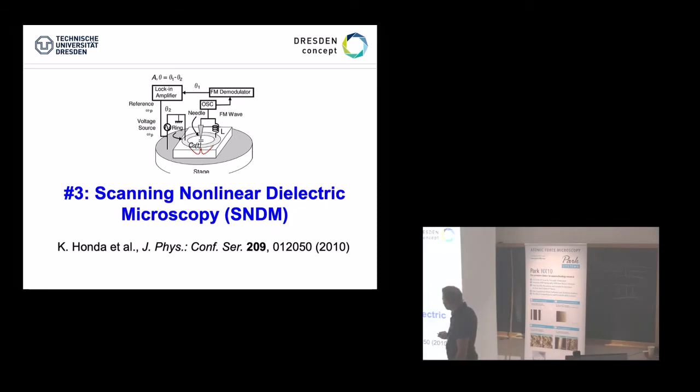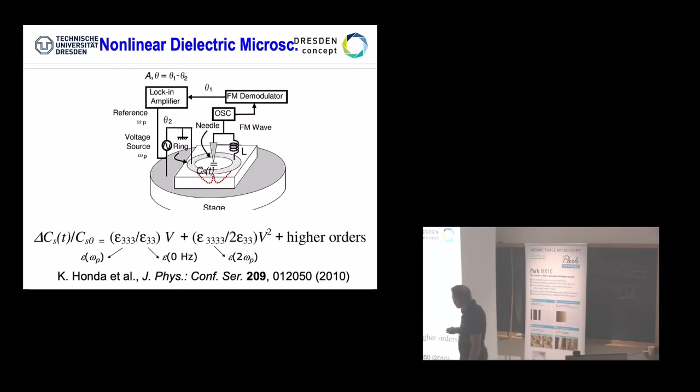We apply this kind of microwave voltage to a certain base plate, that's the grayish area here, put the sample on top of it, have a shielding ring on mass, this is grounded, and then put the tip of the AFM in the center. So what we see here is that we have a capacitance that builds up through the charging of this plate with respect to the tip. And then when you scan your tip, what you're probing is nothing else than the dielectric constants at that microwave frequency. That's clear. And they do this in this experiment, as you can nicely see here, with two different frequencies.